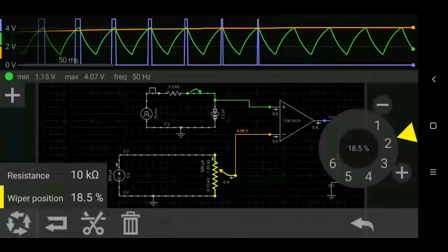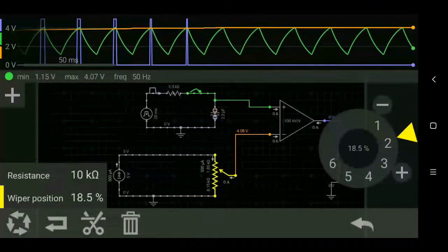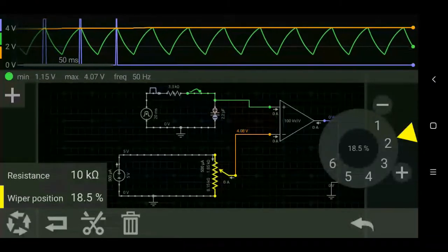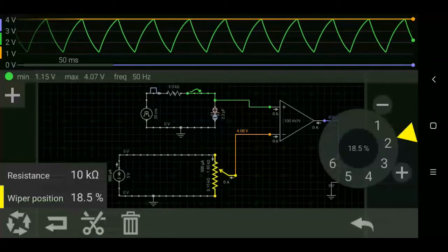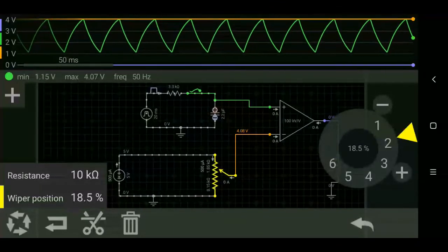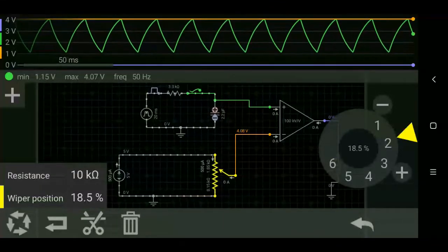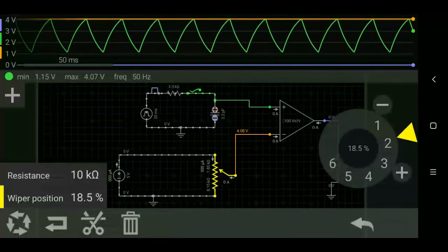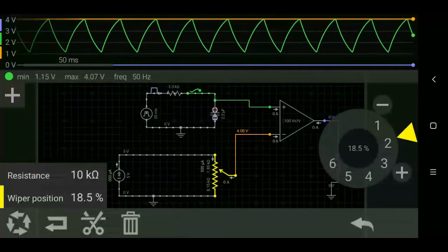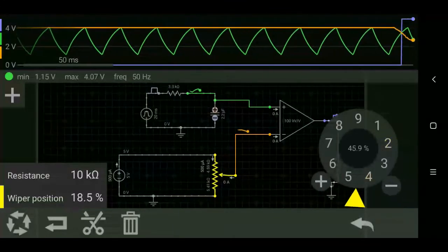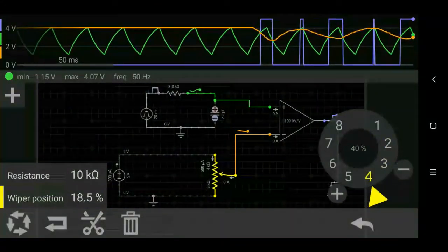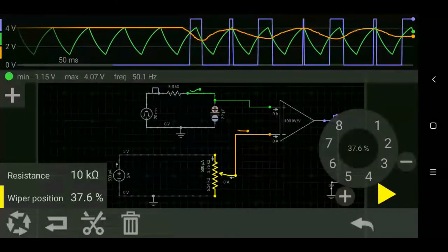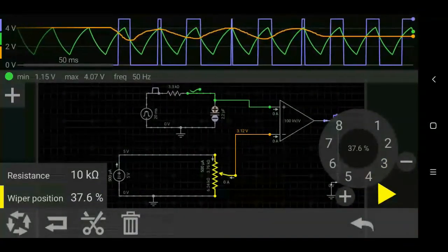So we get a duty cycle modulation from 0% to 100%, and that's good for controlling a servo motor because we want to control the duty cycle from 5% to 10%, and that also can be achieved. And also, if we have an analog input like a slowly varying signal, we can encode that signal into pulse width modulated information.